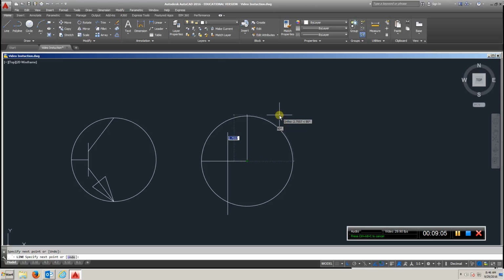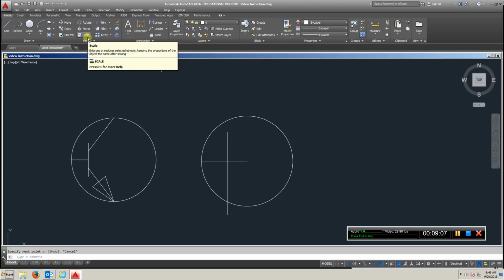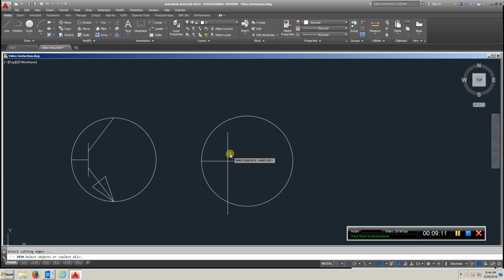Draw that line out to the center. Okay? Hit escape. Go to trim. Choose this line. And then left click that one off. Hit escape. Click this line. Grab that grip and just move it up till it looks like the top.